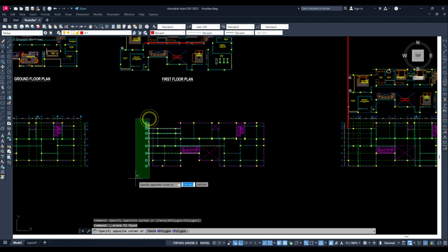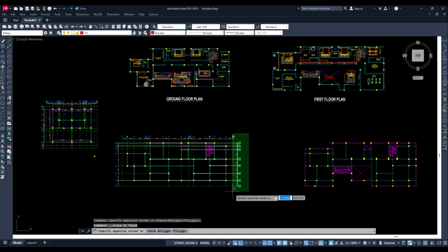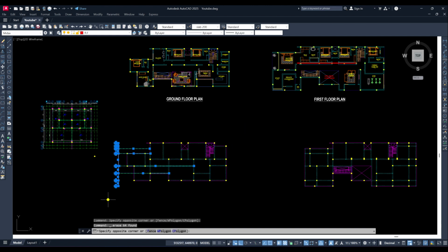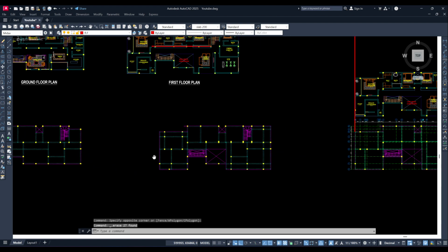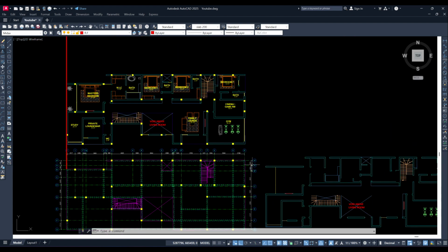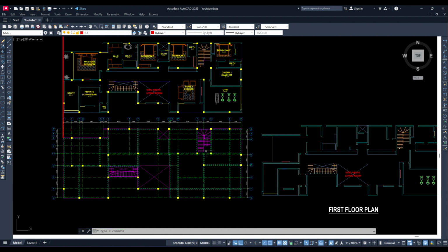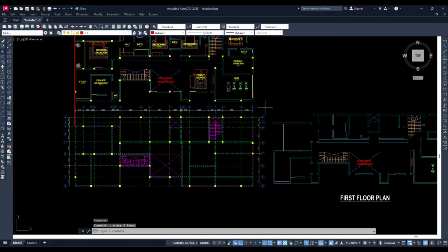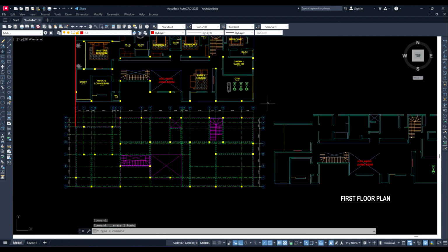So there've been some new grid lines on that first floor layout, so I'm deleting these ones and I'm going to copy the new grid lines that I introduced from the roof beam layout. I want to copy them to the other layout. But first, let me finalize this one, and then before I move those grid lines to the other layouts.